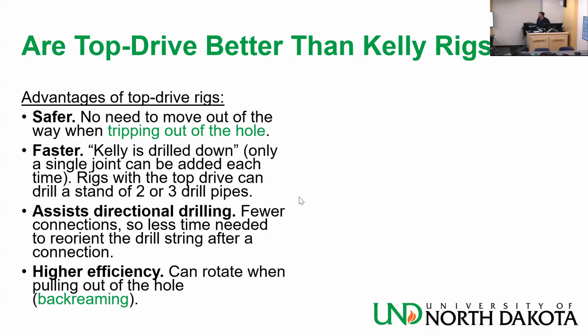I was on a rig in Midland where the bit was destroyed, but we were very close to the end, so they didn't want to pull out of the hole and replace the bit, because if they had to pull out of the hole, they had to back ream the whole way. The operator was very tight with the money, and he didn't want to back ream. He didn't want to trip out. We were drilling at like 5 feet an hour, which is extremely slow.